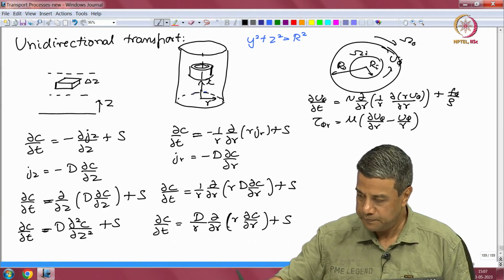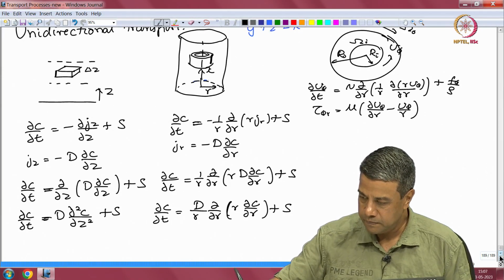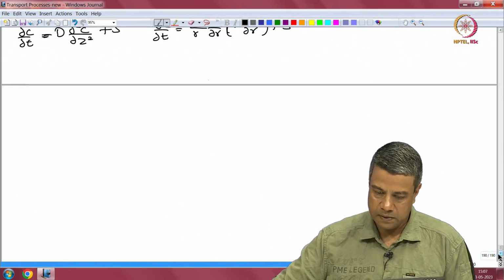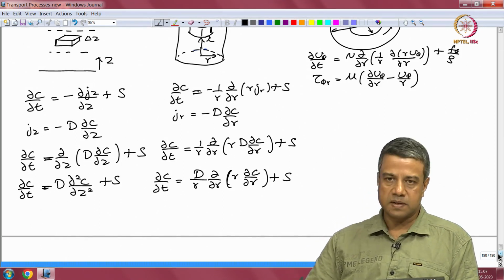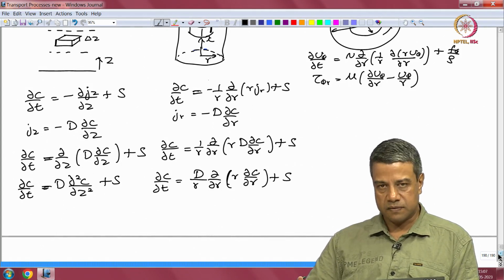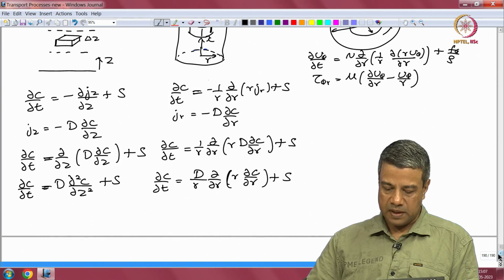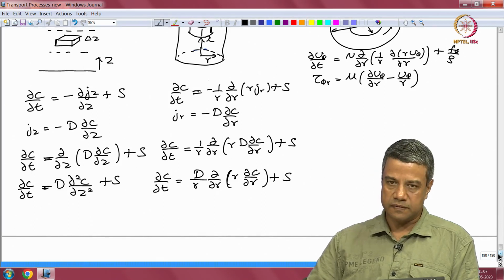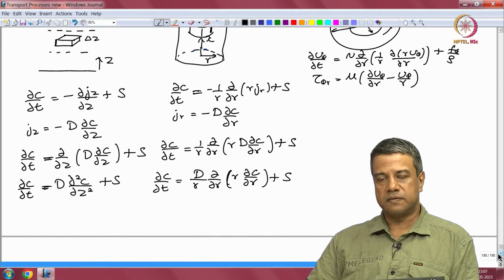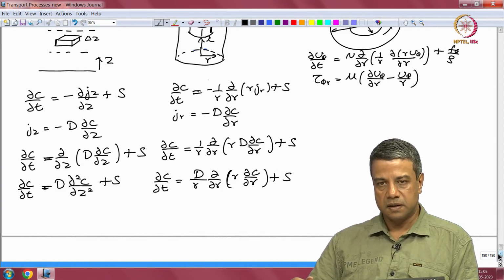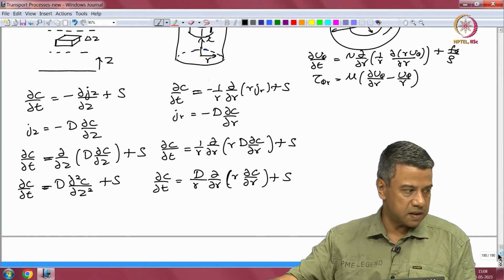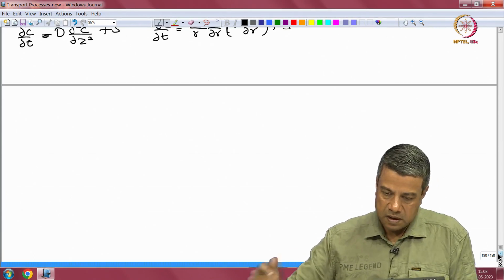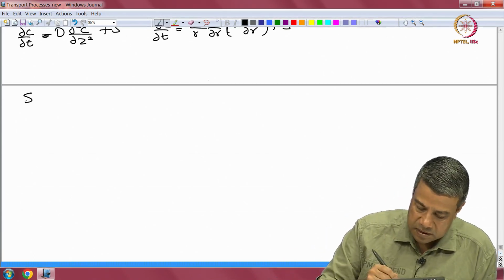So, those were for the rotating flow. And we had solved some steady state problems, both conduction as well as for the fluid flow rotating around the axis in the absence of any sources and for constant diffusivity. And we had also obtained expression for the heat transfer resistance, for multiple resistances due to different cylinders of different thicknesses and different properties. Today we look at another coordinate system, spherical.